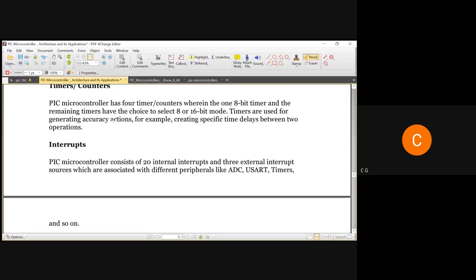Okay, that means whenever the oscillator is a free running oscillator, it has a maximum frequency, but the capacitor that is connected to that particular oscillator will decide the oscillation frequency of the oscillator. You can have an RC oscillator, you can have a resonance oscillator also in place of that, but they are not reliable. A crystal oscillator is more stable, and then internally you program it to choose a particular frequency. Either you have a maximum frequency or you have lower frequencies.